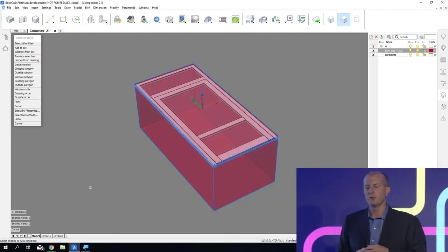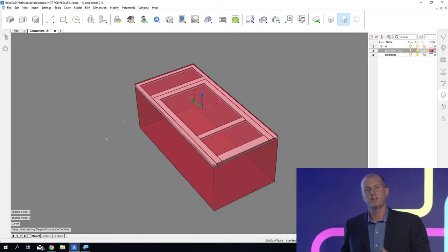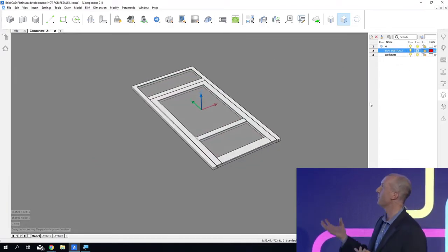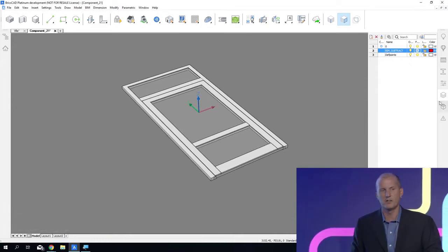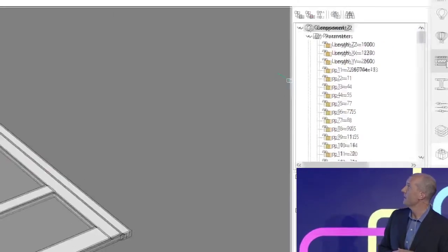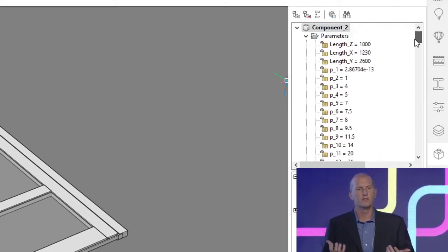So we'll activate the subtract solid that's associated with that component, and we'll use a tool called parameterize. Now, what we can do with this is that then we can parameterize that Revit family into a parametric component that when we select on the mechanical browser, now you're able to see it has a few parameters and a few constraints associated with it.